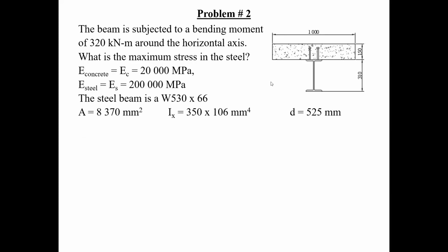Now, here, of course, we have a very typical situation whenever we're pouring a concrete slab over steel girders. We like to take advantage of the fact that the concrete slab can contribute to the properties of the steel girder. And of course, we put in these shear studs, or shear connectors, and these particular shear connectors are called Nelson studs. Therefore, we want to take advantage of this and reduce the amount of steel that we would need, because we're going to take the concrete here and make it work compositely with the steel.